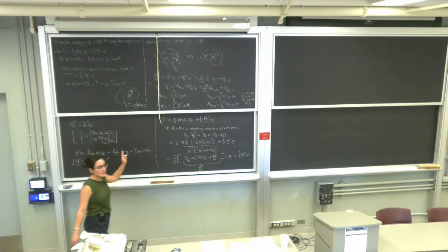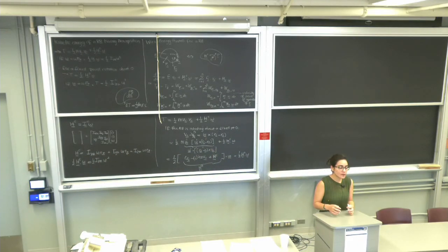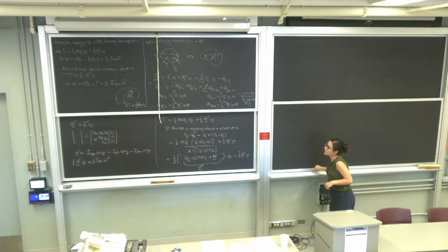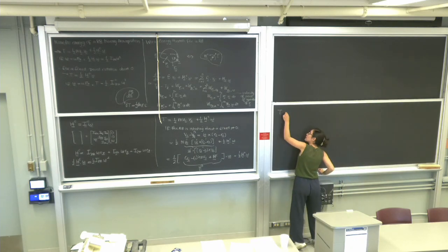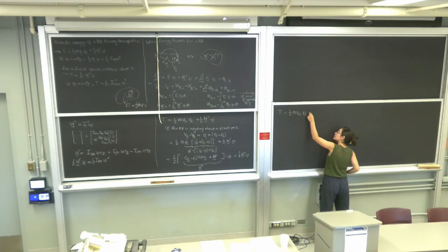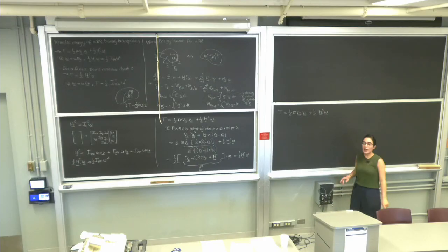Okay, I think now we're ready to prove the work energy theorem. We can prove it, it's derived from the balance laws. It's not an independent equation. So we will start with the expression for the kinetic energy and then we'll derive it. T is half m v_C dot v_C plus half H_C dot omega. And I'm going to take the derivative.